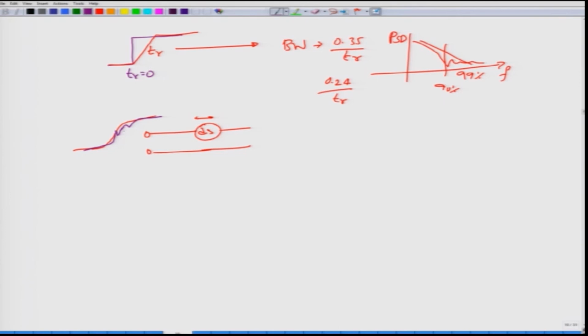So you would see that this amount of small distortions would not be visible properly and it can be completely masked. Okay, so if the rise time is slow, so a slow value of TR corresponds to a bandwidth in the range of say megahertz regime, it will not be able to pick up faults or resolve faults. Why? Because when the voltage is changing from 0 to some value 1, let us say over a time TR, each point is traveling on the transmission line.